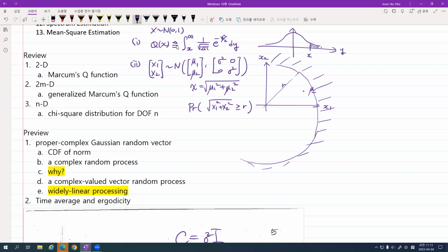Okay, and this can be written in terms of the Marcum Q function, as the first argument talks about the magnitude of this mean vector with respect to the variance, the standard deviation. So here goes chi divided by sigma, which determines the kind of scaling. And then you have the argument that corresponds to this x.